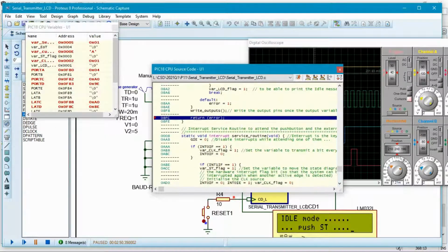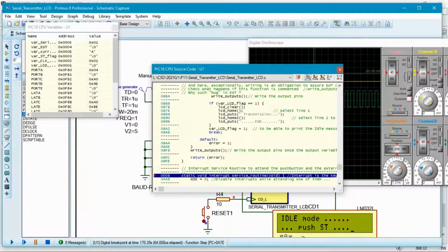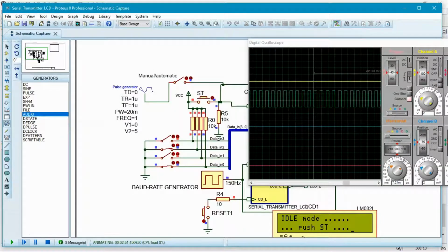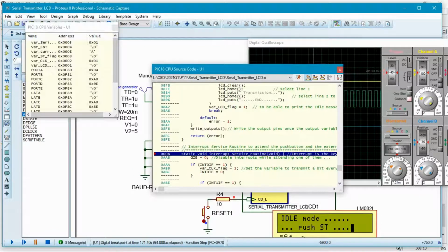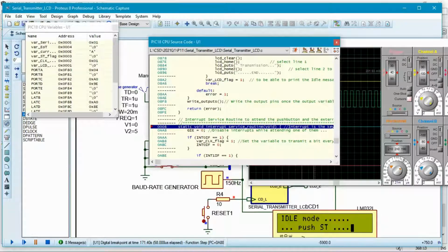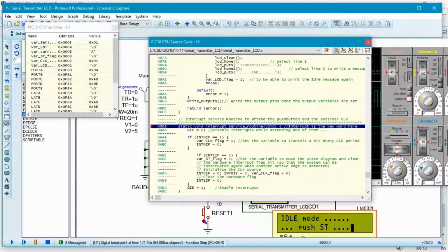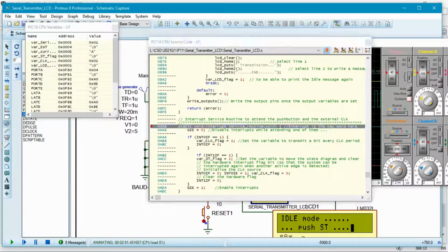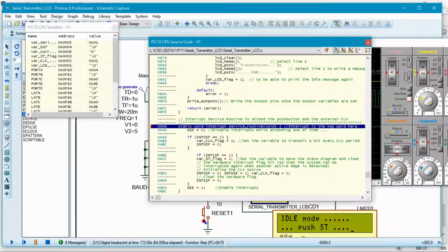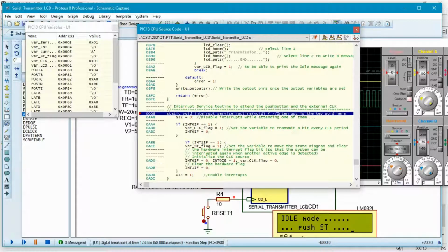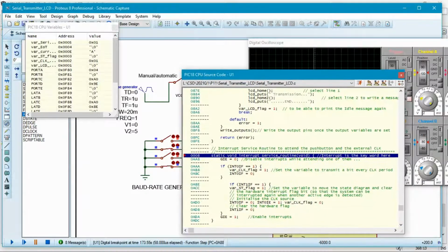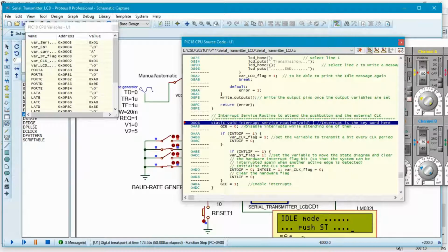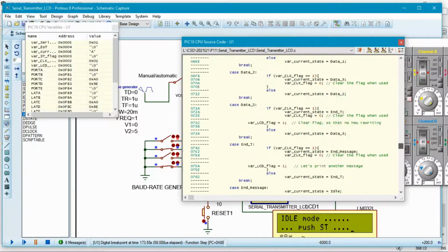For example, you can go down and place your cursor, and let's see first of all if everything is working fine. It should be running step by step, executing one instruction at a time like this. I don't know, but it is difficult to move the system now. You see, an interrupt is detected. Why so? Perhaps you have to go and clear all breakpoints and run again. Yeah, the machine is stuck in this interrupt service routine, and I don't know why it does not go straight to the loop. So you have a problem here. We should investigate that, but we can do that later.